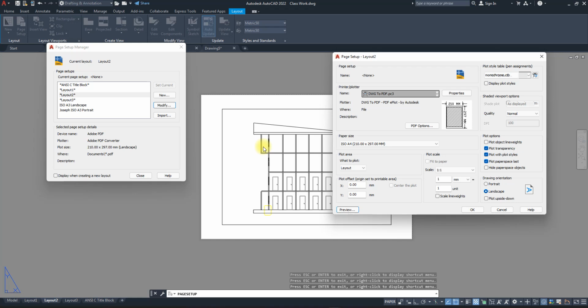X-ref, when we bring an X-ref, is by default going to be faint because it's an attachment. It's not that we select it and now want the property to change transparency. Am I making any sense? If we go to the property to change transparency, it's going to take that transparency property. Am I making any sense? So because this is an X-ref, the transparency still is 0. So that is going to be clear. All right. So we have that.